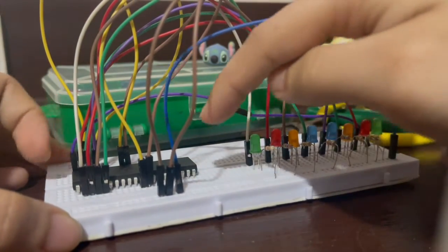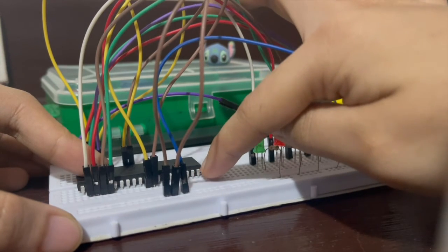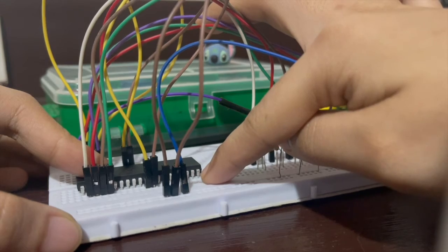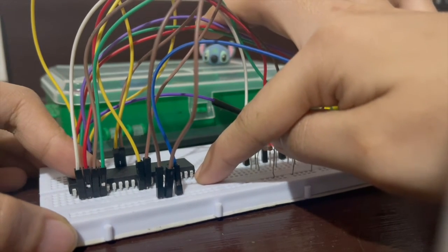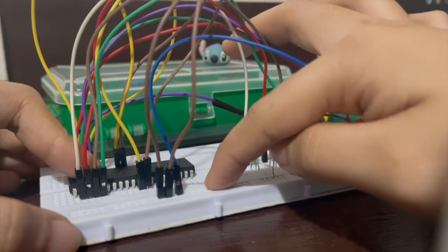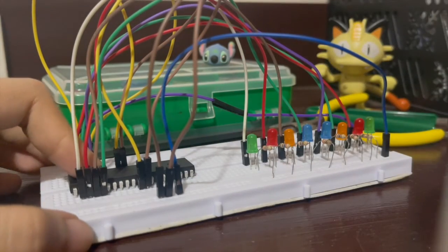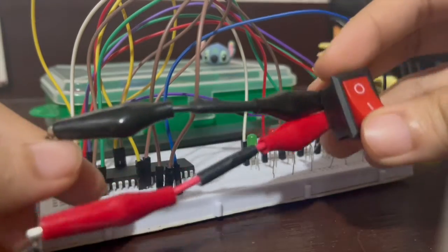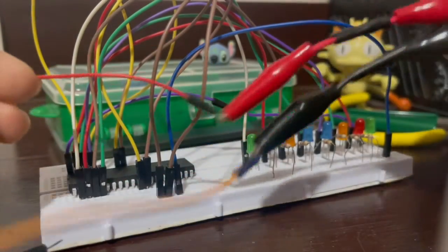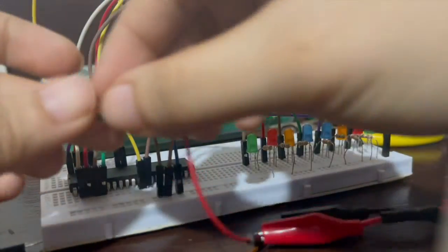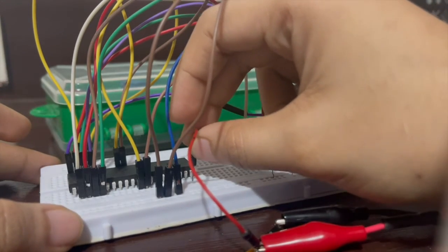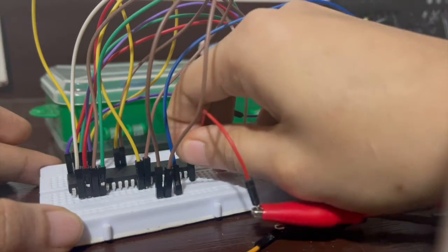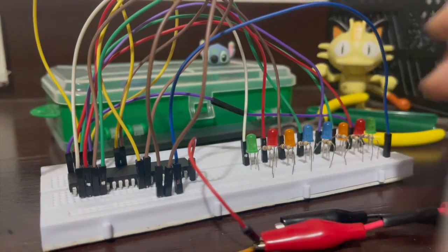We need a switch because it's in the code. So, here is the pin I used for the switch, as you can observe in the diagram posted. For us to connect the switch, connect it here. It has no polarity. So, this red one, we connect it here at the very end. This is the 20th pin. That's what I put in the code. That's RD1.